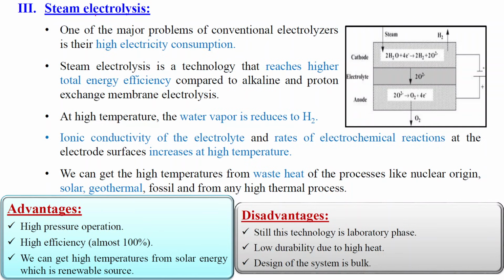Coming on to steam electrolysis. Why steam electrolysis? Since I told you that water splitting at room temperature is very low, if we increase the temperature, then the splitting will also increase. So if we first convert this water into steam and then try to split this steam, its efficiency will definitely increase. One of the major problems of conventional electrolyzers is their high electrical consumption.